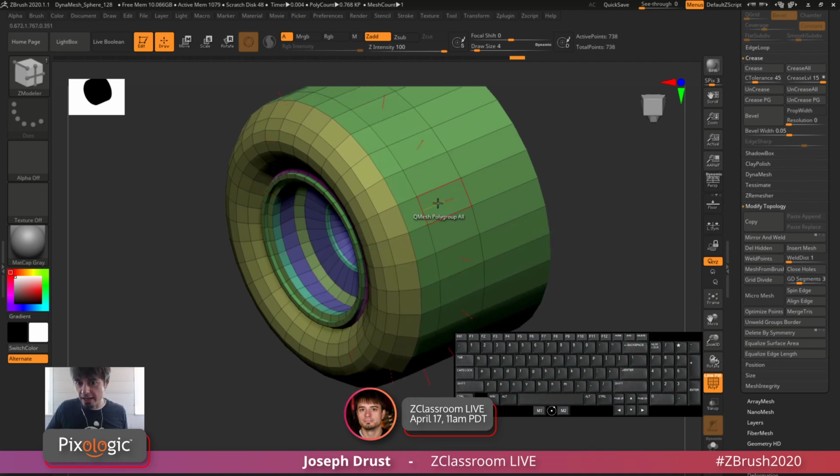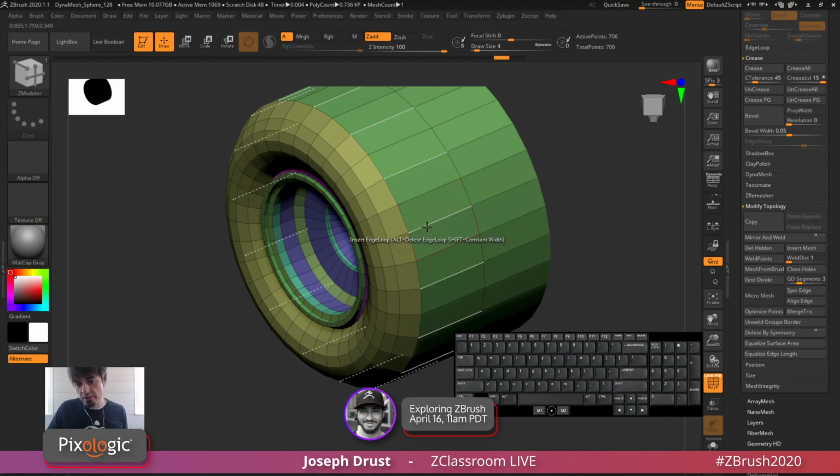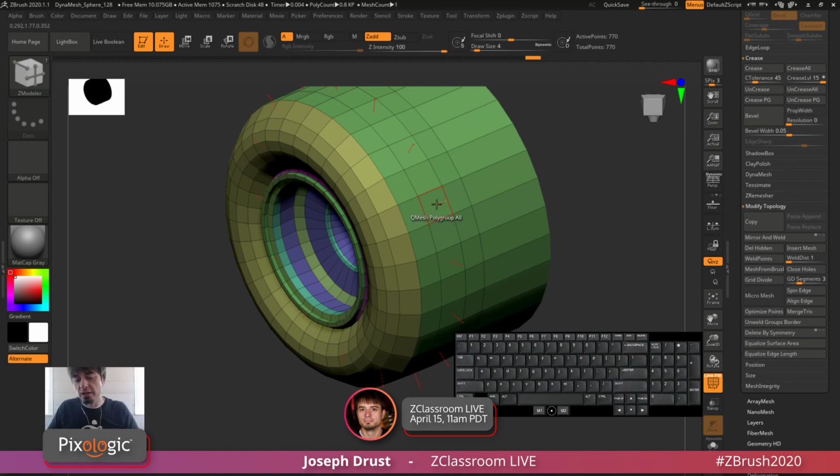So let's say I want to add a hole in this part here, or maybe on this edge. What I'd do first is add some edge loops to protect that area. You do this because if you have a circle, it's going to change the topology around the area, and you don't want long triangles coming from here to your circle. That's going to create crazy artifacts, and it's not going to look smooth.